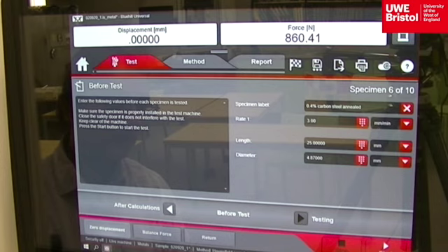Once at that temperature, it's maintained at that temperature for approximately an hour, and then the furnace is turned off, and the specimen is left in the furnace to cool down very slowly, usually overnight. That process of high temperature heating and very slow cooling is a type of heat treatment referred to as annealing. This heat treatment is the only difference between this specimen and the previous one. The test will begin so as to compare the results.